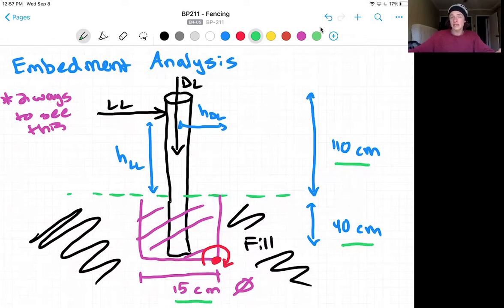The only difference here is before we're looking at the dead load as an axial force centered in the moment as well, centered in that post. So there was no resisting moment to resist the live load forces. However, in this case, because we're looking at the blockout overturning or pulling up and out of the approach ramp, we can use the dead load as a resisting moment force.